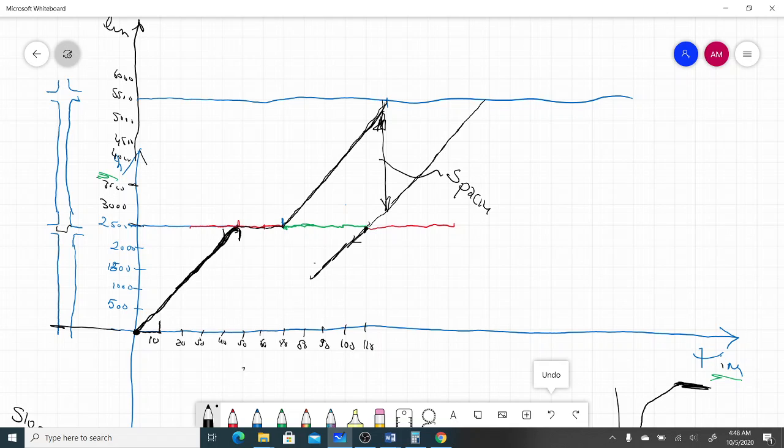So there's a point here where the slope for the last car will start changing, given that this last car will arrive at the last second of the signal. So how do you do it? Since this car will start changing its speed at this point here, you want the same spacing to happen here, which is S here. Let's call this S1. So that's my S1. I want it the same here. And then it will adjust its slope to the first one here.